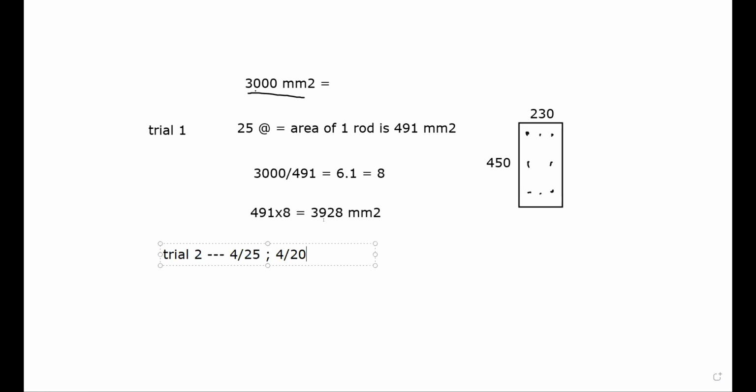You can take it as a project also. You design the entire building with 30 columns or 40 columns, and you design the same building with 28 columns or 25 columns. The same quantity will come. Where you're using 40 columns, you will reduce the size of the steel, to 12 dia rods. Over here, if you use 28 columns, the additional load you have to again distribute. So obviously you will use 25 dia rods, and obviously the cost will be the same.